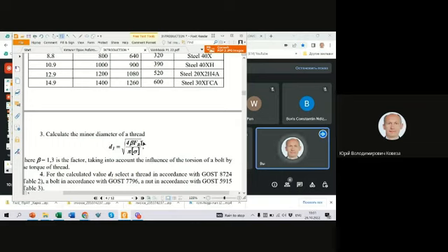Let's calculate D1 and put the result here. If you calculate correctly, your result should be in the region from approximately 8 up to 25 to 28 millimeters. If you use Fb in Newton, sigma in megapascals, result will be in millimeters.